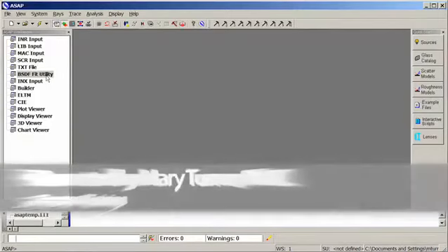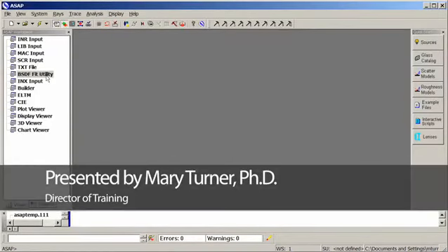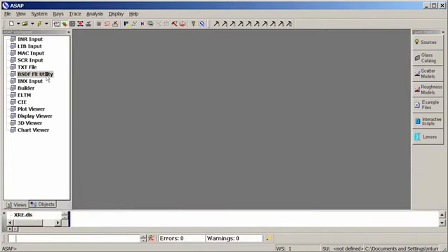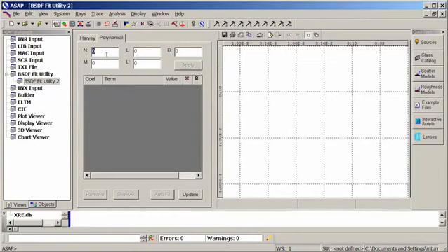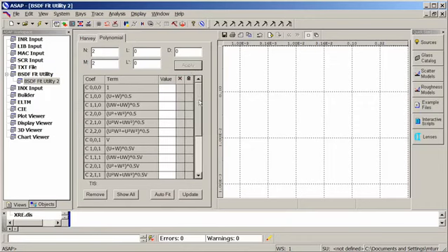More complicated scatter profiles, in particular those that differ significantly as a function of angle of incidence, need a more complicated structure for the BSDF fit. Within ASAP, we're going to use a polynomial fit. The polynomial fit allows you to define a polynomial of n by n terms. Generally, you'd want to start with, for instance, an n by n of 2, and this will give you about 18 terms that can be applied to the fit.